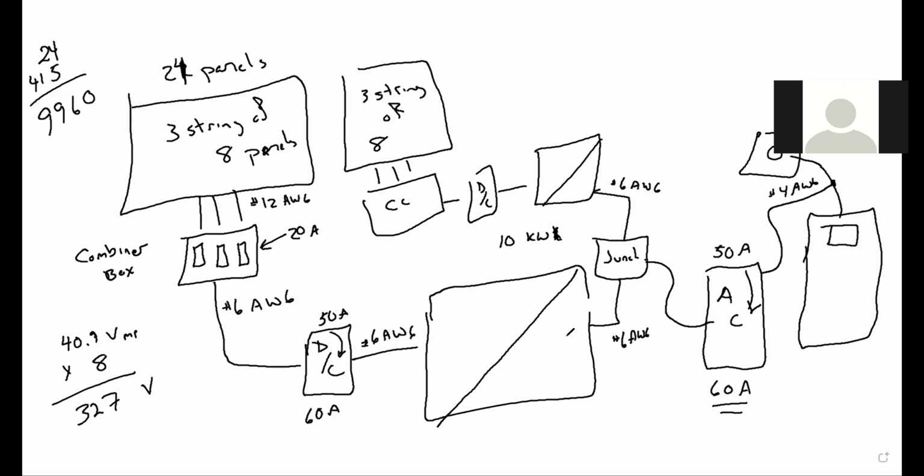Well, what happens with the amps is they increase. What was the amps that we had determined here? If memory serves, it was somewhere around 52 amps coming out of each of these inverters. You can get that either from the inverter spec or by taking the 10 kW, which is what the size was, divided by 240 volts AC, and then multiplying that times the safety margin of 1.25. All right, so if we've got 100, now we've got 104 amps coming out of the junction box into the AC disconnect.